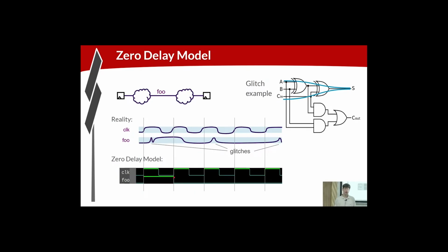Okay, so when we're thinking and reasoning about digital logic, we're only concerned with the stable values, the logic functions at a Boolean level. We don't need to worry about delay. It's the nature of digital logic that you design with certain constraints to guarantee that the timing of the circuit works, and the logic function that you describe is actually how the circuit is going to behave, as long as you design within those constraints and the tools help us meet those constraints. We just need to think about the Boolean logic functions. So that's the last I'm going to say about anything below the level of the Boolean functions that we're encoding.